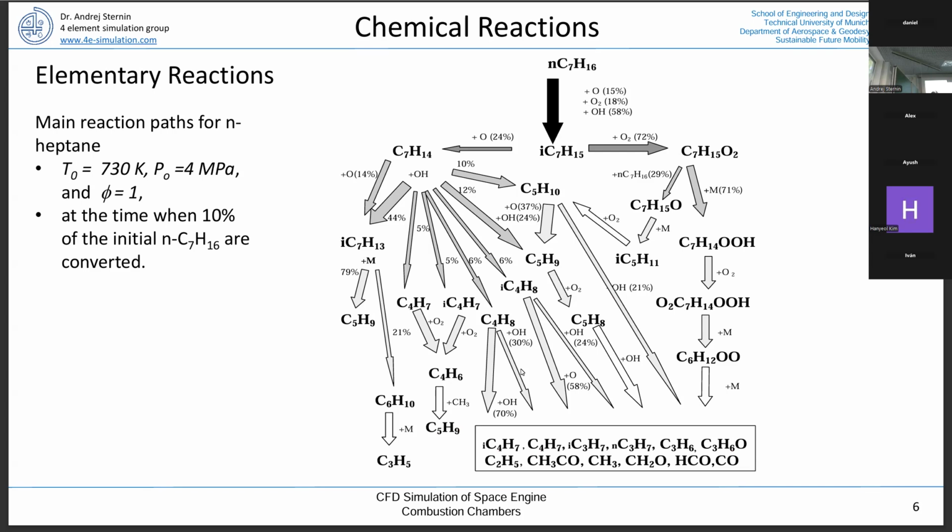So yes, it's N-hexane. So this would be a classical molecule that people are using if they model aero engine combustion. So instead of having experiments or modeling kerosene, which is a mixture of maybe hundreds of different kinds of species, they say we just deal with N-hexane, and this is complicated enough.